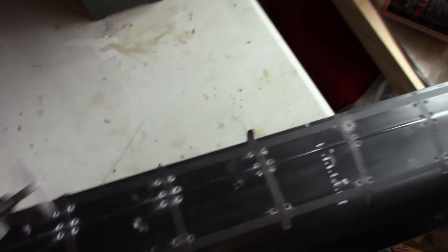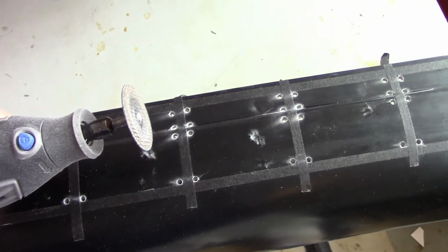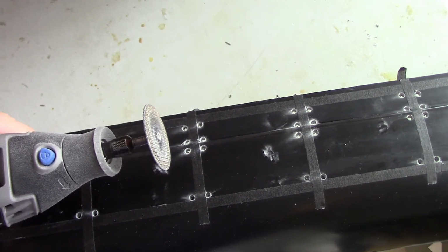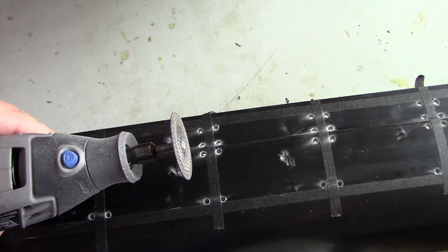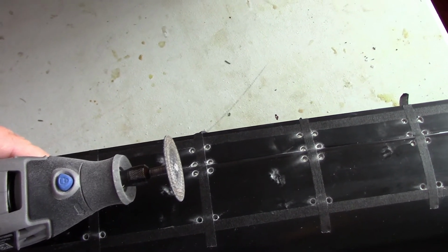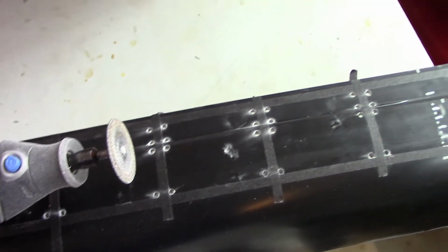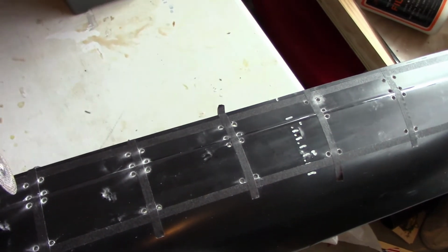And then you'll notice the Dremel wheel spins a certain direction, so when I'm using the vacuum, I always make sure at the point of contact with the hull that it's spinning towards the vacuum. It'll make sense when you see the dust come off of it, it'll go right towards the vacuum. If you have the vacuum on the other way, it'll still catch some of the dust, but it'll catch less because the dust will be moving away from the vacuum suction. So I'll videotape some of this, you can get the feel. I expect this hull will probably take a couple hours of Dremeling to do both sides.